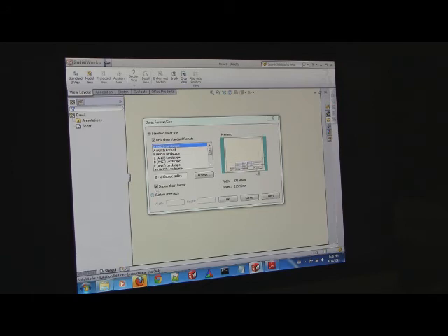You see the display sheet format thing? You see in the preview all this stuff here, all the text and the tables? We don't want that. That's for people at Lockheed Martin. Don't do it. It's bad. It's like version control and who signed it. Press that display sheet format and it will go away.